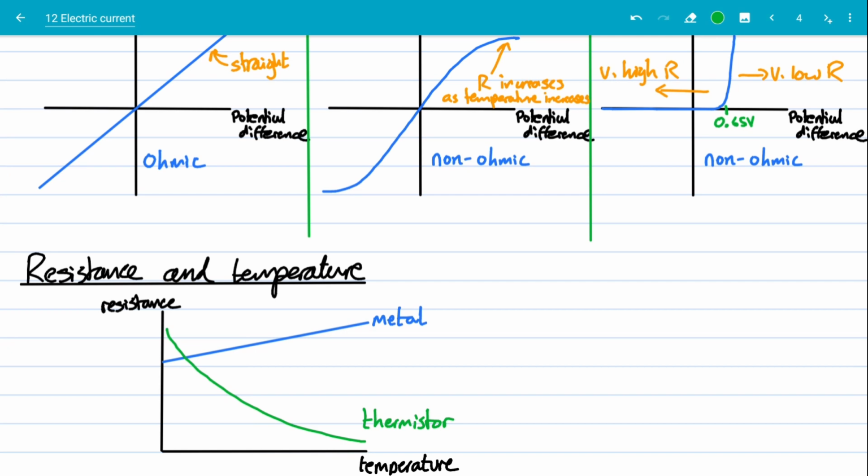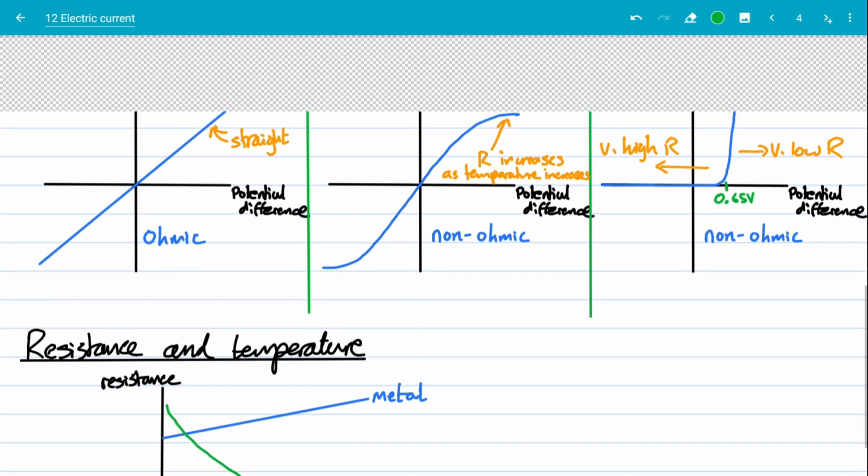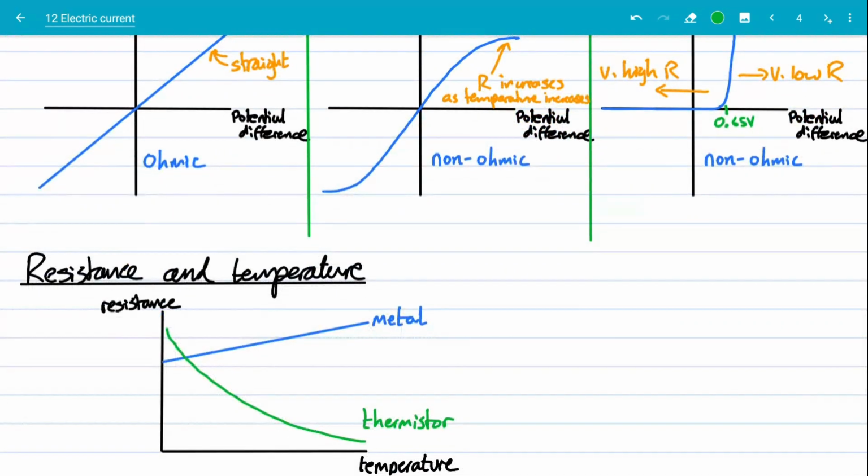Whereas with LDRs, light dependent resistors, it's the same basic principle, but we have chosen that band gap. We've modified the metallurgy, we've modified the materials so that the band gap is related to visible light photons. They carry enough energy to promote electrons into that conduction band. And we can even combine these semiconductors in interesting ways, extrinsically doped semiconductors, to produce things like diodes and transistors. But that all lies beyond this A-level course.